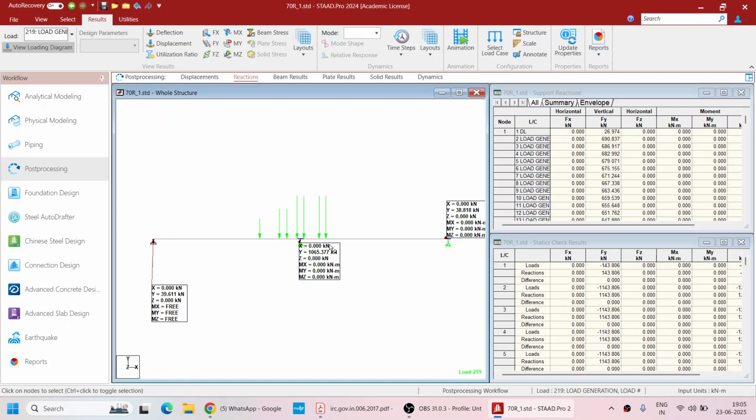In our calculation for maximum reaction there will be a value of 97.5 ton something, and when you consider the UDL for ISMB 600, there will be 1.21 kilonewton per meter load.